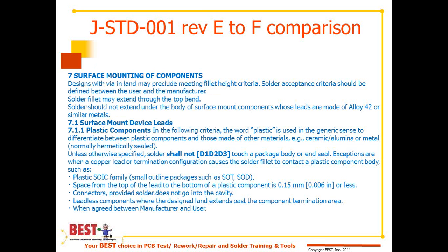Also, the solder fillet may extend from the top bend. The solder should not extend under the body of a surface mount component whose leads are made of an alloy 42 or similar metals. Under 7.1 for surface mount device leads, plastic components, they talk about the plastic components that's used in a generic sense to differentiate between plastic and other materials such as ceramic.